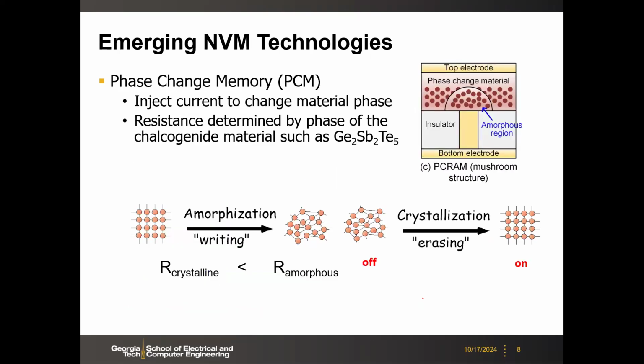And then the phase change memory, PCM. This one typically uses material based on the chalcogenide family. Chalcogenide is a group 6 material, below the oxygen, like the telluride. Typically, it's based on this GST system, germanium, antimony, telluride, and this typical ratio 2:2:5 is used.